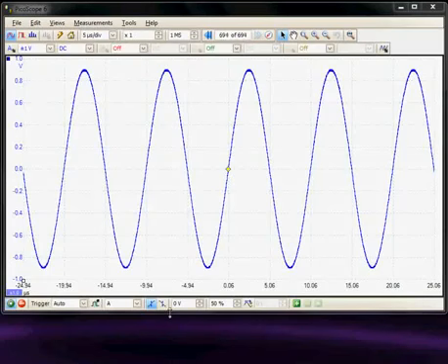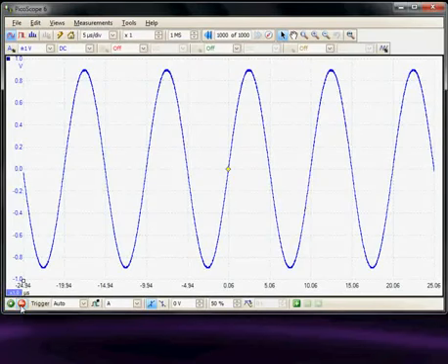The input trigger conditions can be defined in the trigger toolbar provided along the bottom of the main display panel. The first two icons are to stop and start the acquisition. So at present the data is being acquired, and if any data of interest is being displayed and captured, this can then be stopped for further analysis, and then the first icon would restart the acquisition. The remaining icons are to define the input trigger conditions.